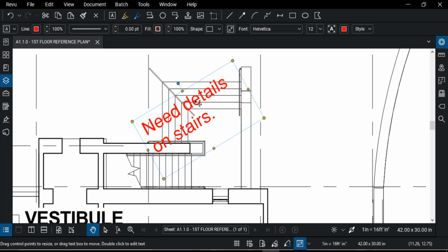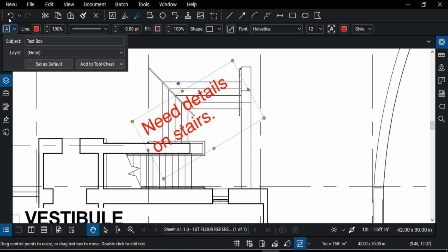So now that I have it selected, as soon as I created this markup, you'll notice up at the top I now have the properties toolbar where I can go in and I can change some of these properties. So I'll start out here far left. I can click that drop down arrow there and you're going to see subject. Now subject by default goes to whatever tool we selected. Changing it is going to provide you the ability to filter and sort your data within the markups list. It's also a very powerful tool within the markups list because you can utilize it in custom columns as well. And so we'll see that a little later. So I'm going to go ahead and change that subject, and I'm going to change this subject to contractor.